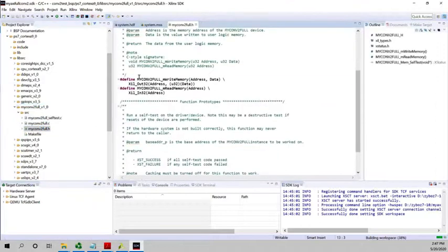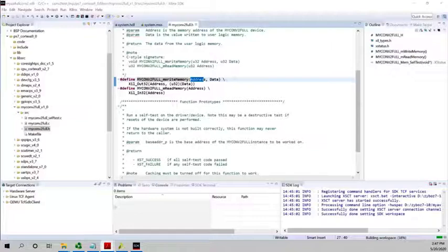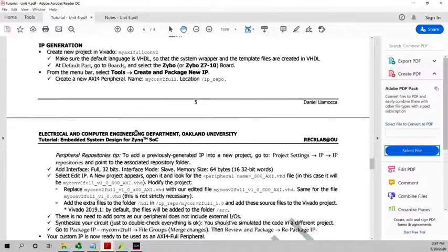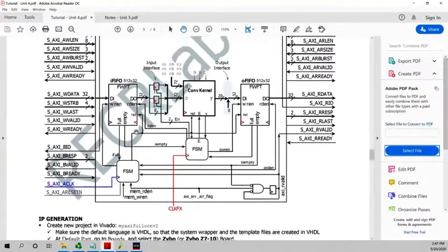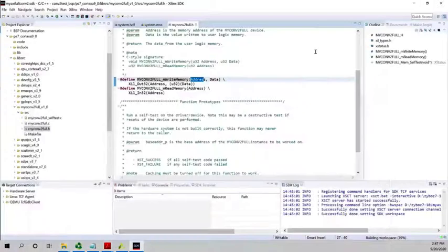Like I said, it's just my COM2-Full. Write memory, you provide the address and the data. What is the address, by the way, if you don't remember? Just a moment. The address in this particular case doesn't matter. Any of the 16 addresses will work the same, because we are not decoding the address in this FIFO based example. So you write on any address, it will write on the FIFO regardless. Okay, that happens when you write or when you read.